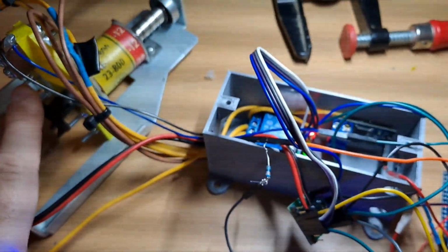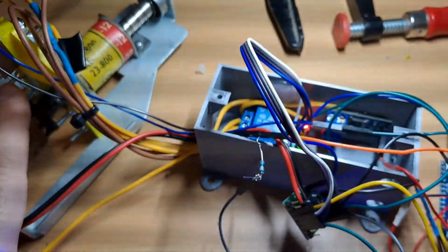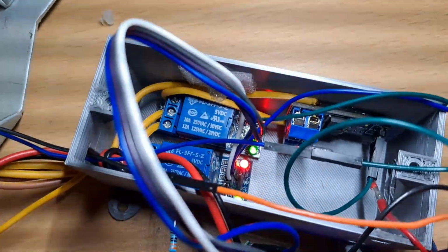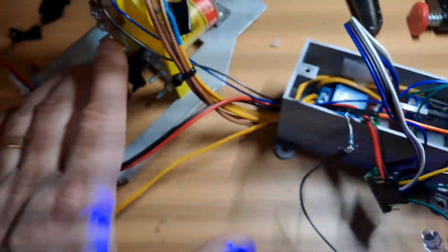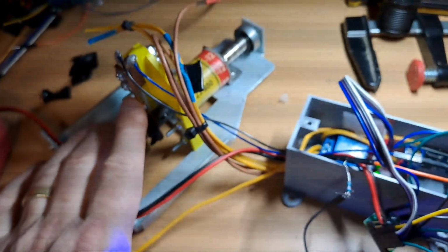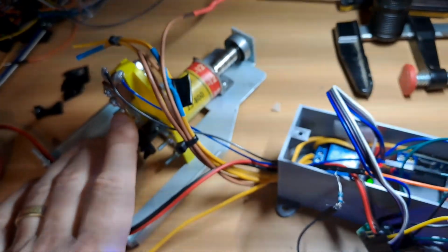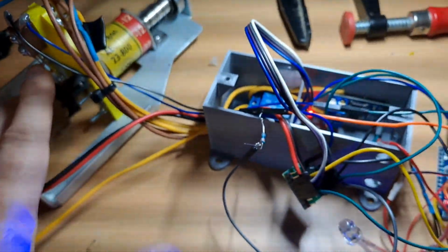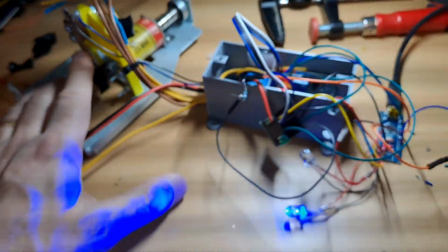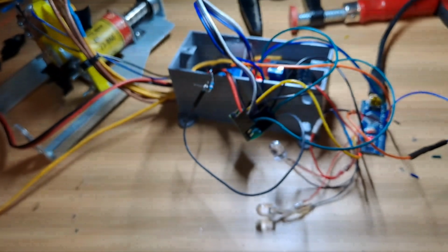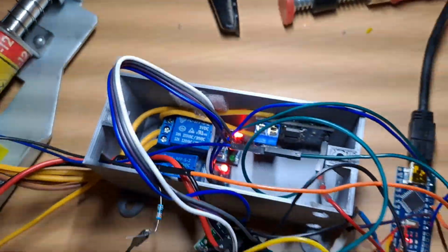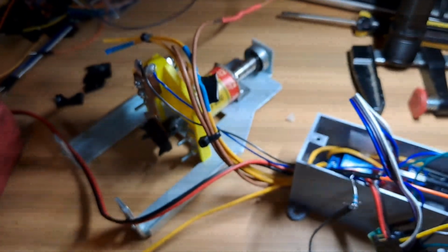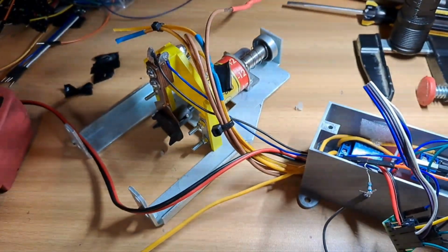So in a normal state, this thing will fire the ball out, but if the ball remains there longer than 12 seconds, then those two relays right there will reconfigure the wiring for the VUK so that it's powered like an old school EM. And it'll get 75 volts through a fuse, and it'll pulse it for 30 milliseconds until the ball is no longer on the fork switch. And when that happens, the light goes off, relays click back over, and now the thing is configured the way it had always been and powered through the MPU like it normally is.